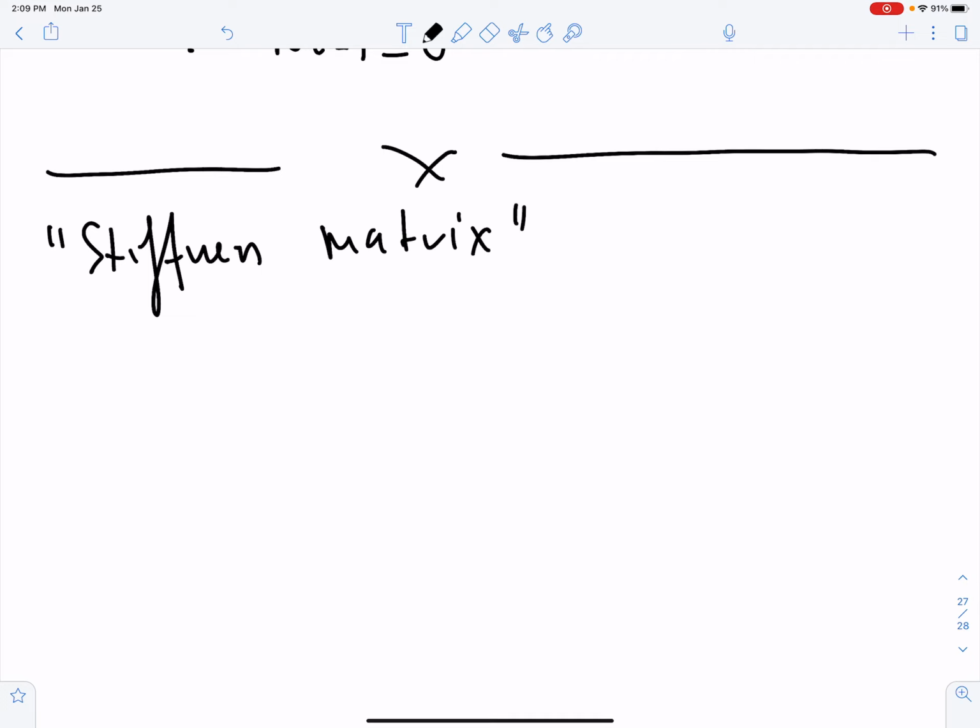Okay, stiffness matrix. Every time you talk about stiffness, everything you've seen, for now, you look at springs, for example. What is stiffness? It's a property of a spring that relates displacement to force. A linear spring gives you a linear spring coefficient, K. So F equals K times X, for example, where X is the amount of displacement and F is the force.